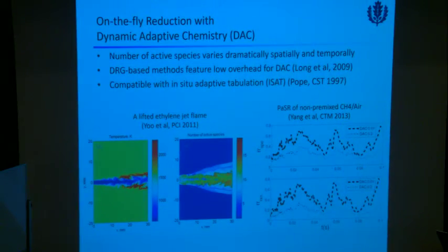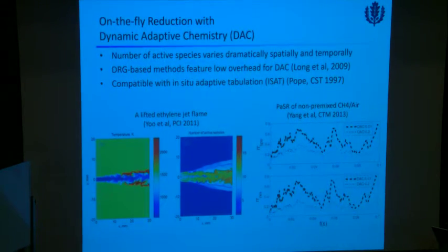Because otherwise you will have a conservation issue. Mass must be conserved. The key thing is using DAC, the purpose is to save time. So typically people use an implicit solver to solve everything. If you get more reacting species, you get a larger implicit core to solve. So for example, here you don't need to solve any chemistry, so it's non-stiff, right?